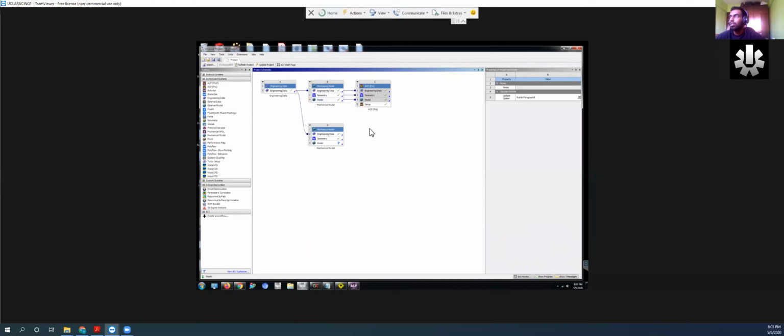Okay. So once you've updated the project, you should see all green ticks. And once you have all green ticks, what you want to do now is go to ACP Pre under Component Systems, and this is where your composite systems come into play. You click and drag ACP Pre, and then you drag it over to the model box that you earlier settled. So in this case, I'm going to drag it over to this one here.